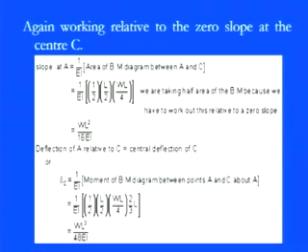For that, the slope at point A is equal to 1 by EI times the area of the bending moment diagram between point A and point C. So by keeping those things, we have 1 by EI into half into L by 2 into WL by 4, because this length is L by 2 and this height is WL by 4. So we can simply go for half of the area, since we have half of this rectangular part. So the total between point A and C will be equal to WL square by 16 EI.